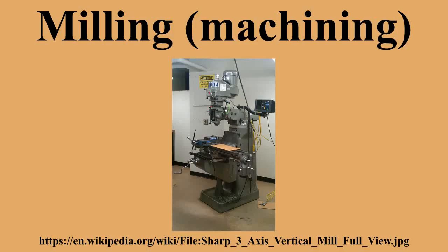Horizontal boring mill: large, accurate bed horizontal mills that incorporate many features from various machine tools. They are predominantly used to create large manufacturing jigs, or to modify large, high-precision parts. They have a spindle stroke of several feet, and many are equipped with a tailstock to perform very long boring operations without losing accuracy as the bore increases in depth.